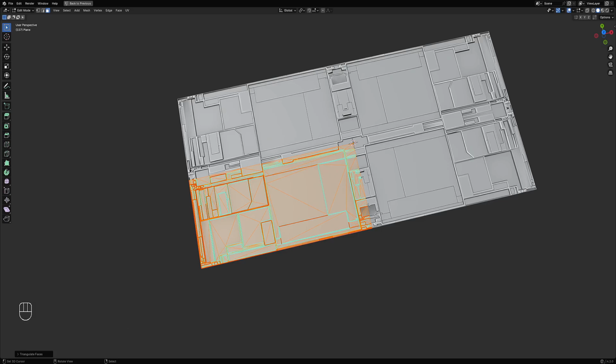And the shading errors are mostly caused by overlapping vertices and faces. So you can just repair that manually. And you can build a library of this and then save it and then use the asset browser to basically drag and drop it to your scene, using again the asset browser.